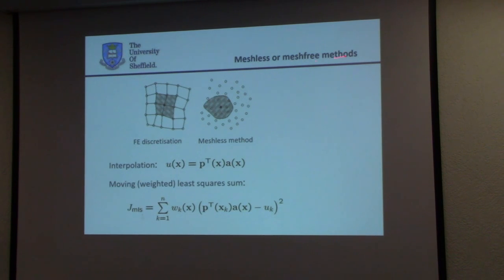In addition, finite elements have the very nice property that their interpolation is 1 at the node. Which means that you can easily impose Dirichlet boundary conditions. In this case, you have multiple nodes in this domain, which means that the imposition of Dirichlet boundary conditions, that your displacement is 0 here, or that you impose a displacement here, which is so convenient and easy in finite elements, is not so easy anymore in meshless methods.